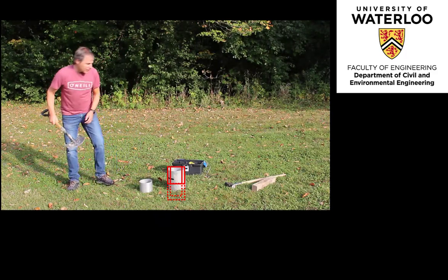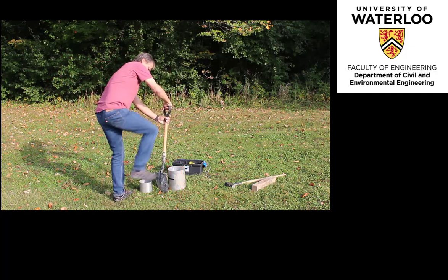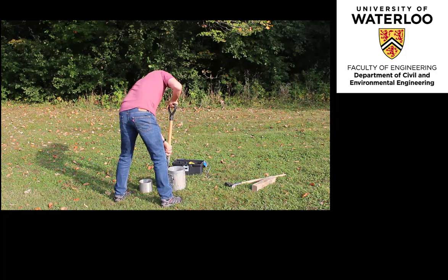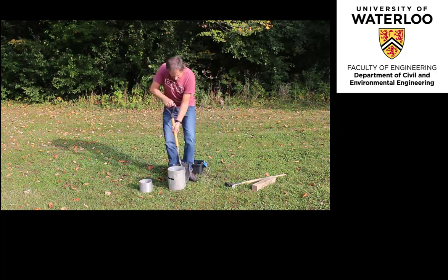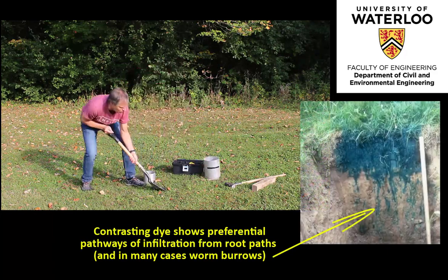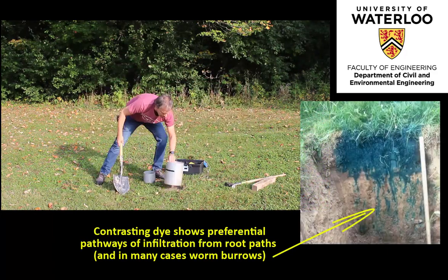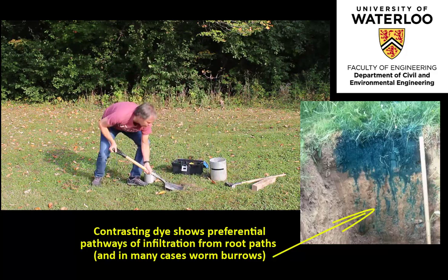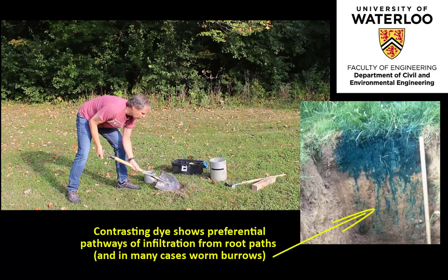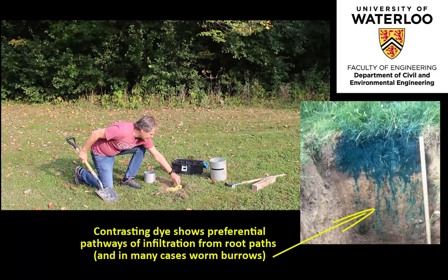conducted. Removal of the sod will allow the water percolation to be more represented by the primary porosity of the porous media rather than enhanced macropores created by existing roots, worm trails, or dead or rotting root pathways. It is noted here that these types of macropores can create notably enhanced pathways for infiltration to occur, which can capture a significantly larger volume of receiving precipitation than the underlying porous media.